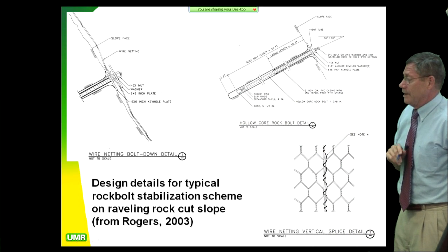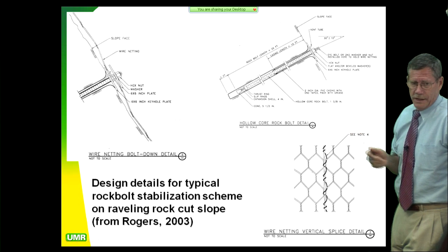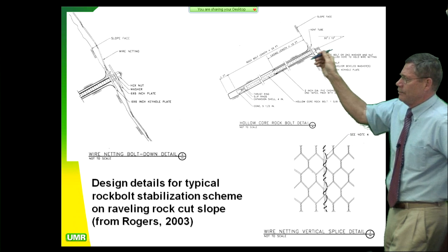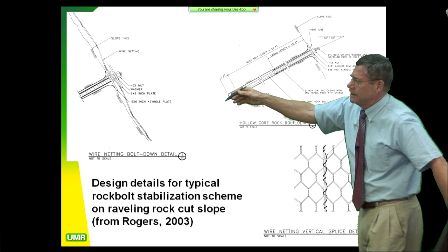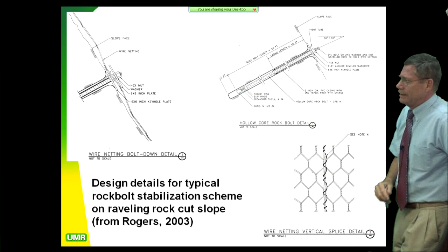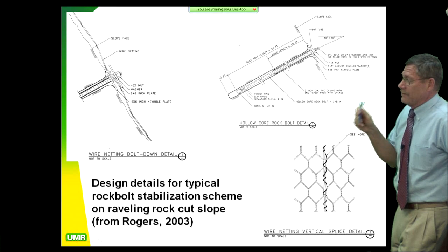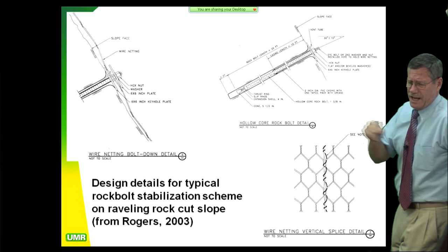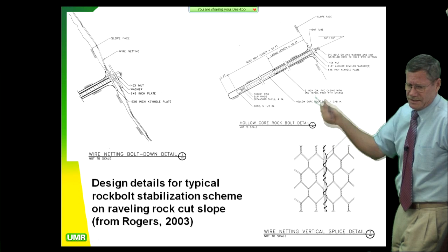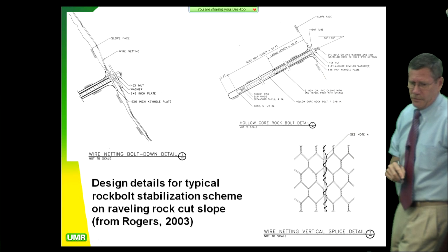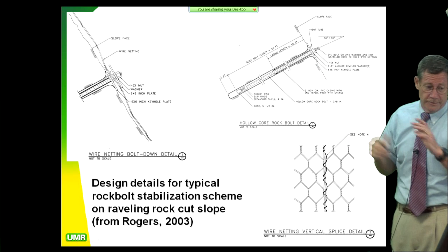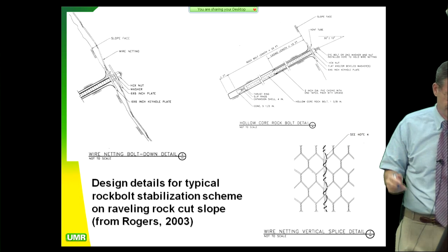I am a big advocate of hollow core rock bolts because I get much greater grout penetration and much higher anchorage with them. Far and away exceeds just the regular threadbar bolts. But you have to tell the contractors and have them sign all sorts of affidavits that they're bidding hollow core bolt jobs, or they'll miss it.